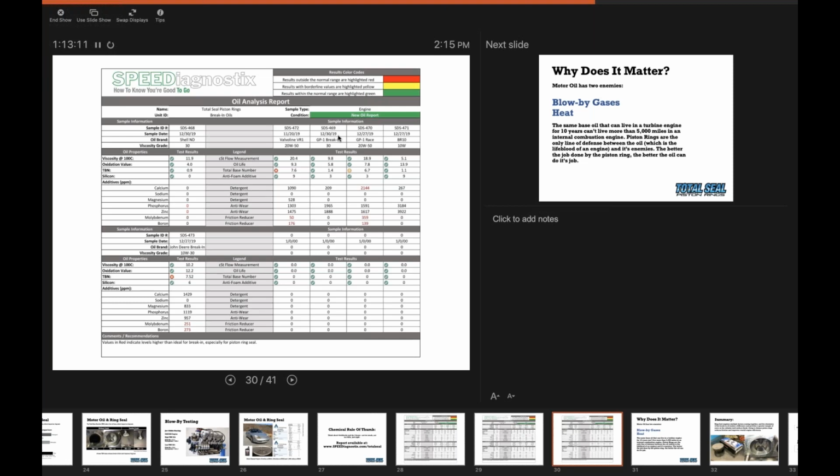Again, back to, hey, 46% of the friction is the ring. That still means there's other friction to be had by reducing viscosity, by improving the lubricity of the oil through friction modifiers. So that's where that whole process, the synergy of working them all together, could really unlock the full potential of the engine, which we did and won a bunch of championships doing it.